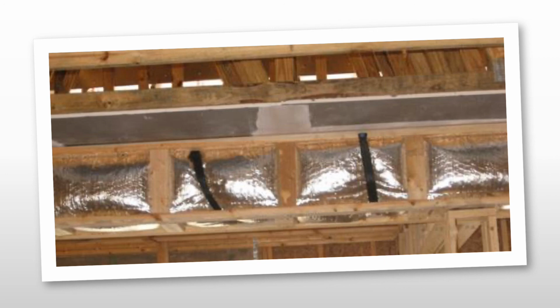Also see in the top of this chase up here, you've got a layer of sheetrock and then a moldy 2x4 in the truss up there. So you've already got mold growing there, and then you've got sheetrock on top of that for fireproofing, and then they fire taped it right in this area. When they got all that done, they built the framing down under there to frame in this chase to make it decorative. And now you're going to have sheetrock all the way around that.